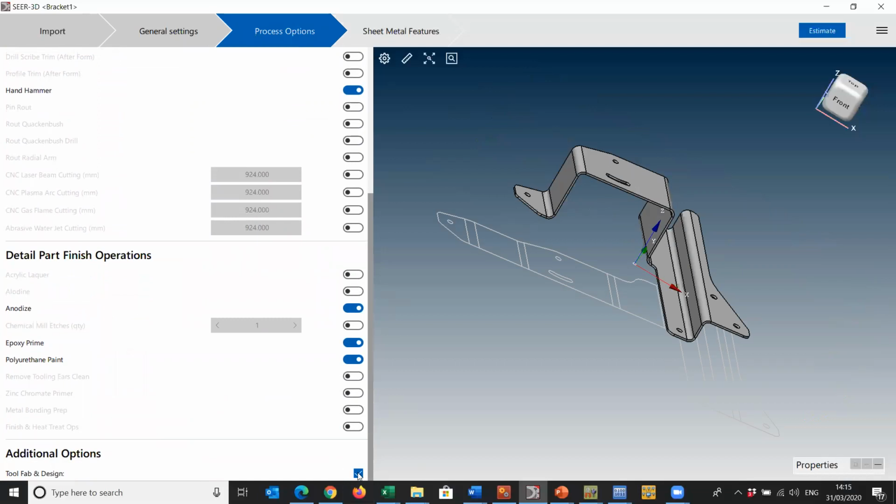In that folder is an Excel workbook with lots of parameters, things where you can set the defaults, bounding box excesses, and the process rules associated with the part family that you're trying to create. Within there, you can also select the tooling list. So what tools do I need? Do I need machine control media? Do I need bolster blocks? Whatever you need to produce a part for the part family that you wish to create.